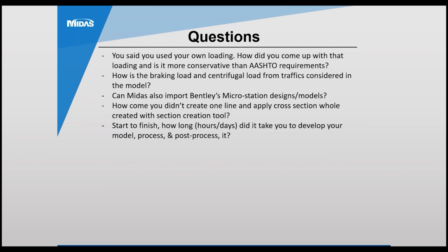Sure. Good question. They were spread footings for the location. Actually, it was pretty good soil up on the mountain. There's a lot of bedrock up there. So everything was on soil foundations, or spread footing foundations. And for the soil interaction, we used the forces that were developed. We assumed a fixed condition, and then we considered the effects of overturning and those types of things based on the forces we pulled out of the model. So we didn't do the actual soil interaction inside MIDAS, but we did it like you would for a typical spread footing, outside of MIDAS.